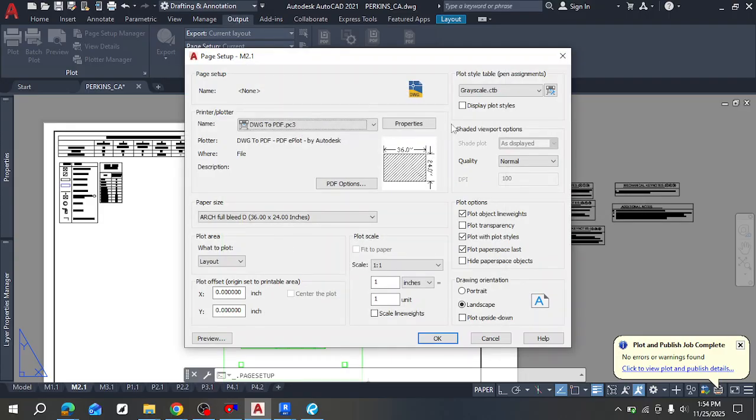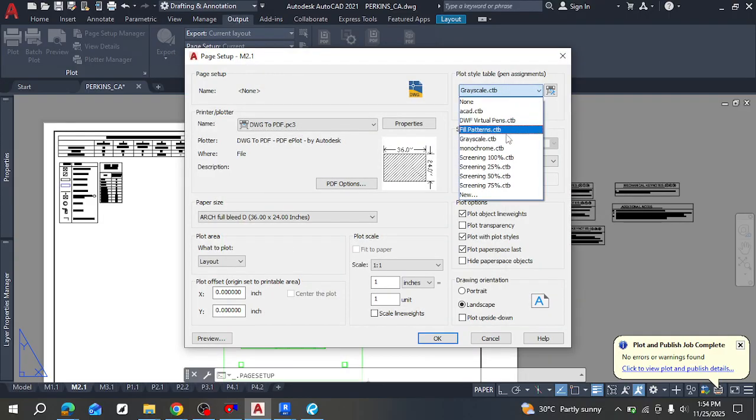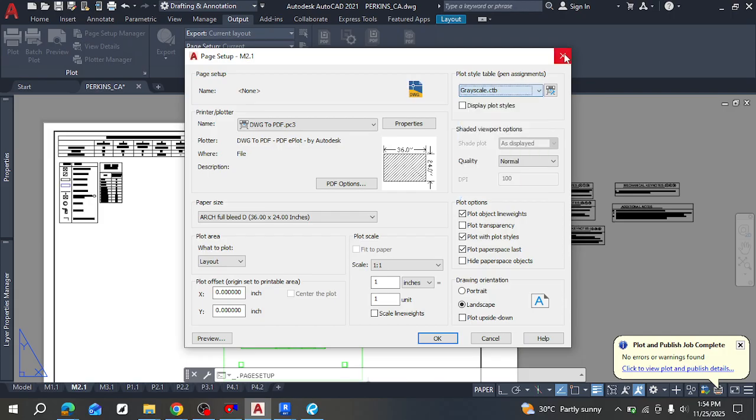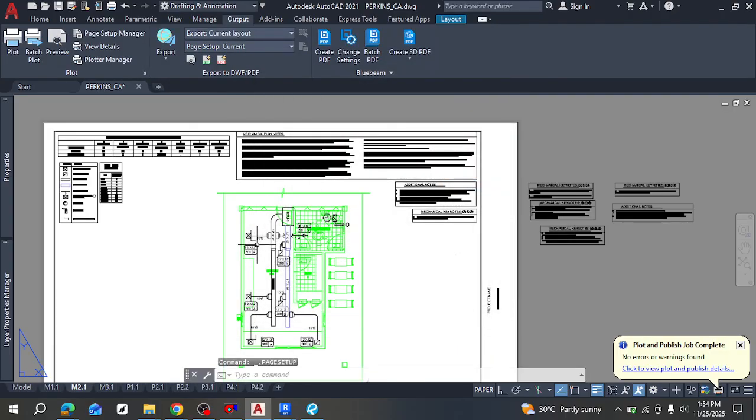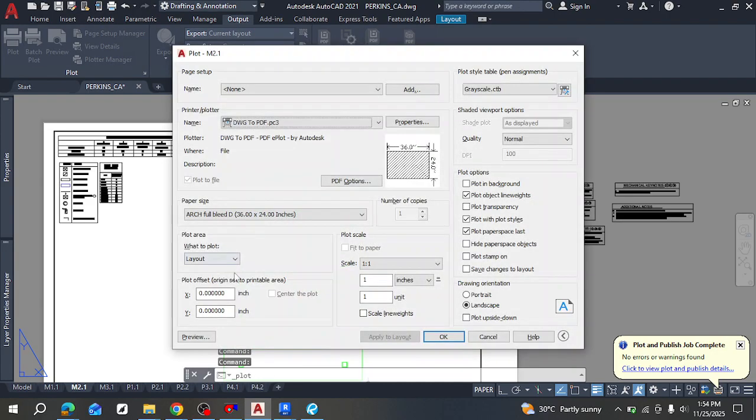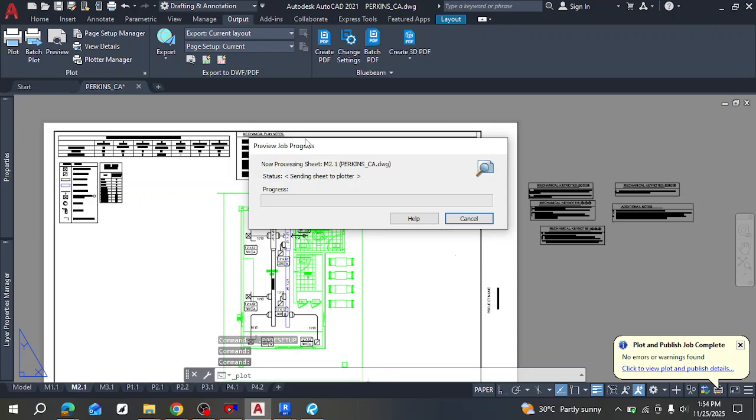Modify. The only thing I change here is grayscale instead of monochrome. Grayscale means that, depending on the color you select, it shows a thickness or transparency of that line in different shades of gray. So now let's print it out for you to see. Control P will print out only that page. So let's preview what the printed page will look like. If you see now,